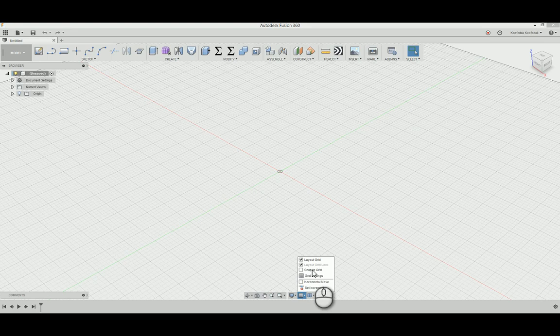Yeah. What is snap to grid? Oh, it's like when you move something and it'll snap to those little points on the grid. So if you want something to be 3.13 inches, it won't let you. It'll snap to 3.15. Okay. So you're gonna just turn it off because it's so annoying just for a beginner, unless you have tolerances and you're an engineer and you want things to always snap, okay? And also turn incremental move off as well.